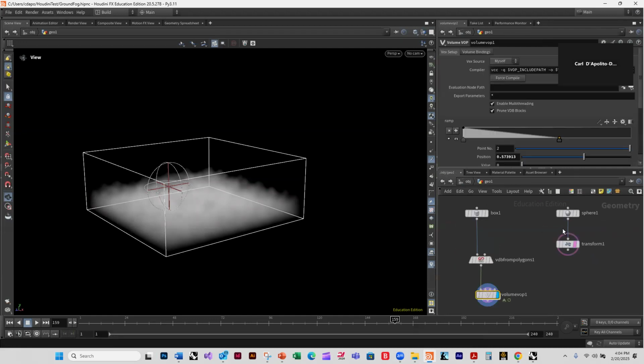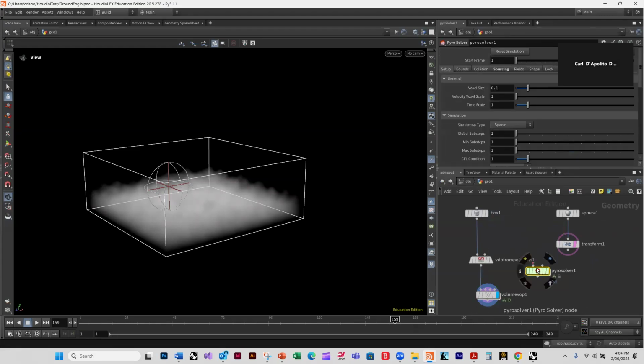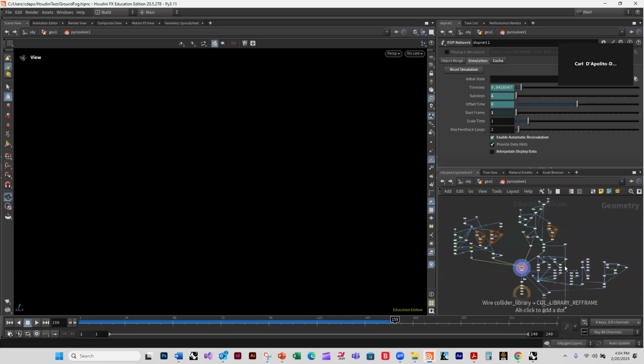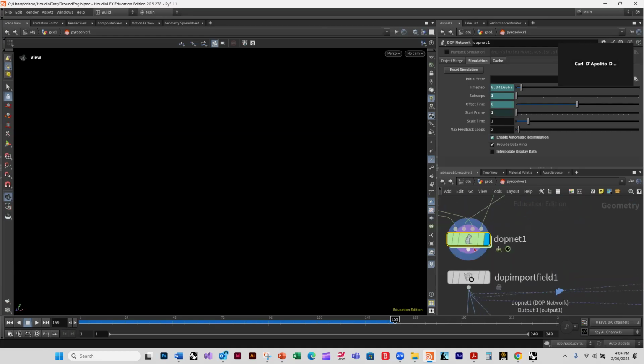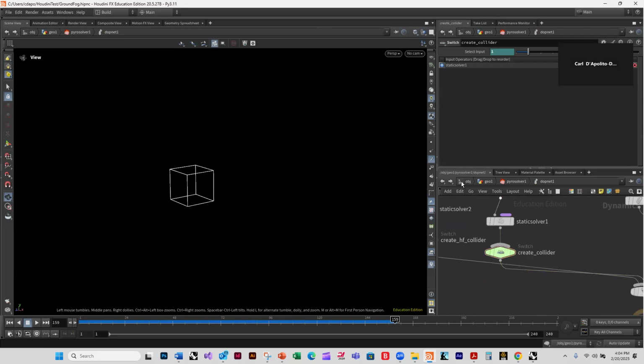And that is both frightening and good because it means that whenever you get a node from Houdini, like if I go here and I load the Pyro solver, okay, and I put it here, if I right click and I go allow editing of contents, and then I dive in here, it'll expose the way that the Houdini people created it, okay? And then within here, by the way, there's another one and another one, okay? It goes on forever.